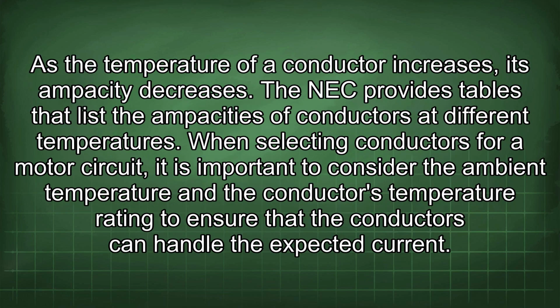Temperature rise is another factor that affects the ampacity of conductors. As the temperature of a conductor increases, its ampacity decreases. The NEC provides tables that list the ampacities of conductors at different temperatures. When selecting conductors for a motor circuit, it is important to consider the ambient temperature and the conductor's temperature rating to ensure that the conductors can handle the expected current.